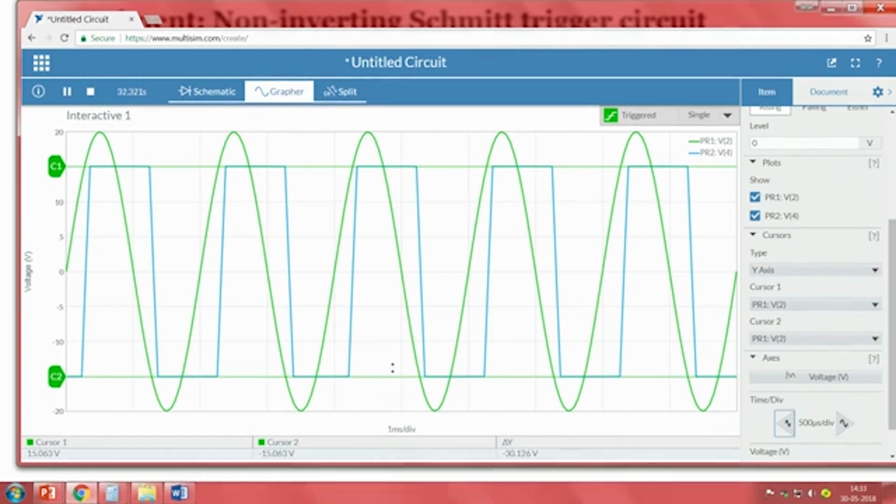Why do we not check? When the input is greater than this value, it started to change. But why is the output not greater than before? In the previous case, the input signal is smaller and the output voltage is higher, but why in this case is it not? Because the saturation voltage of the op amp is plus or minus 15, but the input is higher than that.